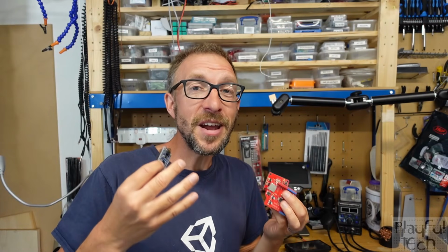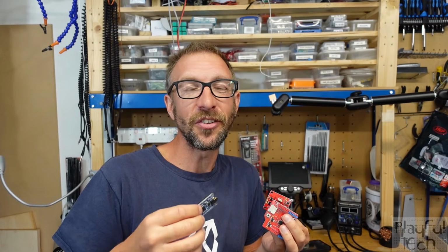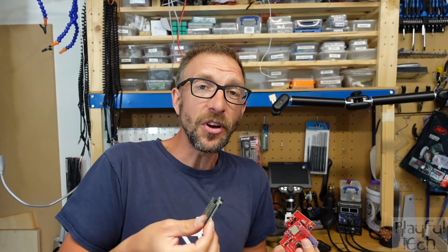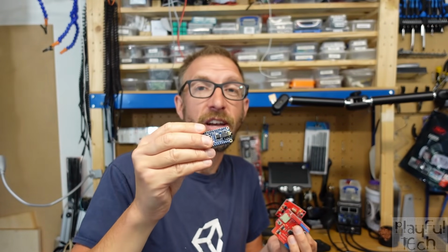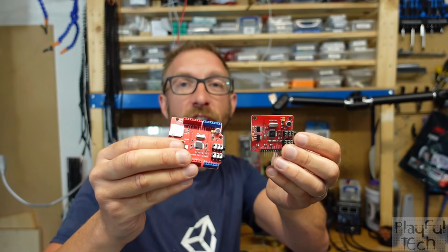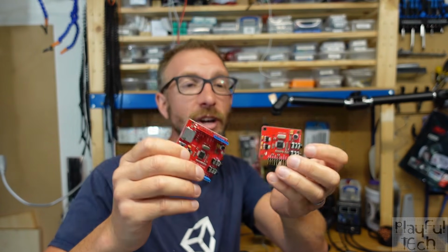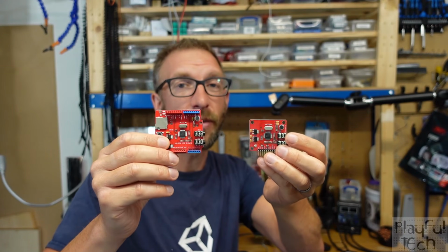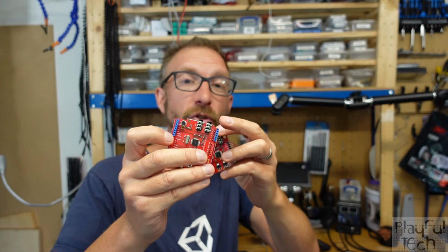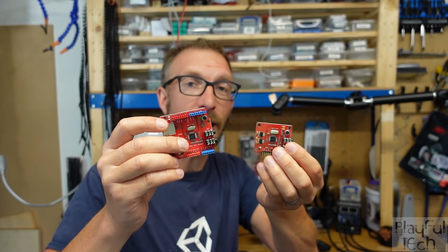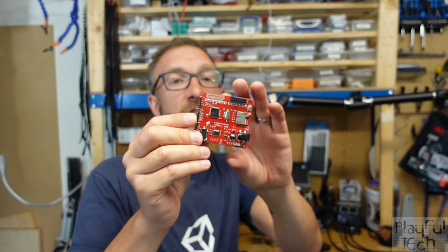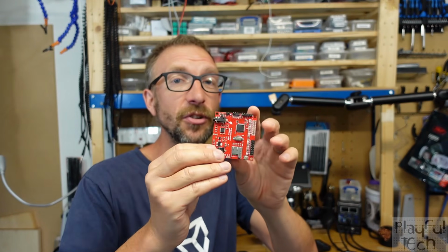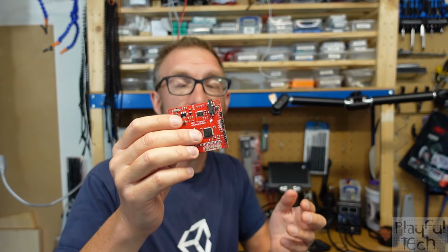And of course there are still many other audio boards on top of the ones I've described in this video. Some of those that I've used in the past include this Adafruit soundboard, which is based on the VS1000D chip. I've also used these two boards, both in the form of a shield and a breakout board, that use the VS1053. Now these are great if you want to record audio as well as play it back. And I've also used the WAV Trigger by Robertsonics, and this is based on a completely different architecture again. This uses a custom ARM chip.